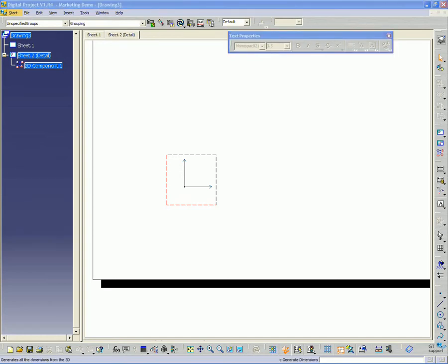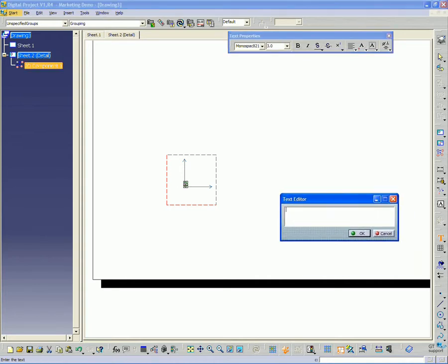So I want to create some text. So I go over to my text tool object over here on the right, and click near the origin to create some new text. And I'm going to say Slab Name. So I want to indicate the name of the slab in the model, colon. And then holding down the control button, I'm going to press enter to get a new line. It takes me down one line. And then I also want to say Slab Volume, colon.